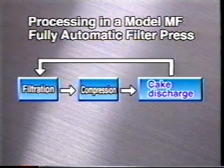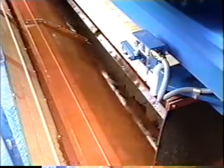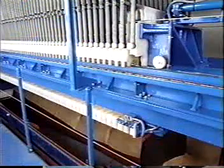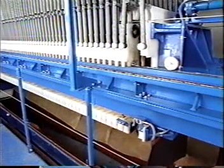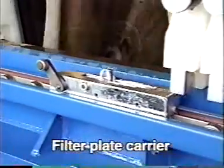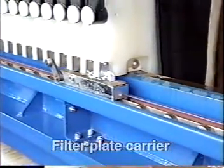Next, the cake is discharged. First, the drip pan opens, and a conveyor under the filter press begins to move. At the same time, a hydraulic pump opens the movable head which had tightened the filter plates. The filter plate carriers then open the filter chambers one at a time, discharging the cake.